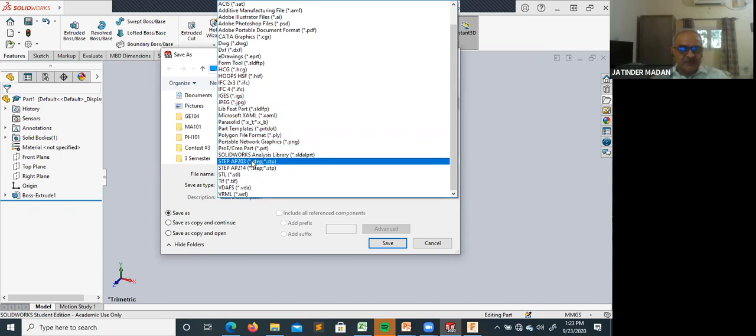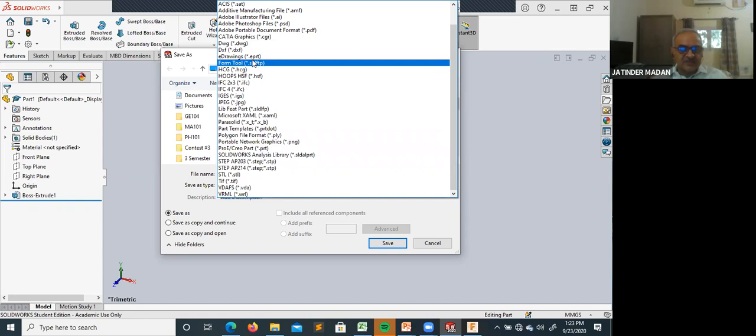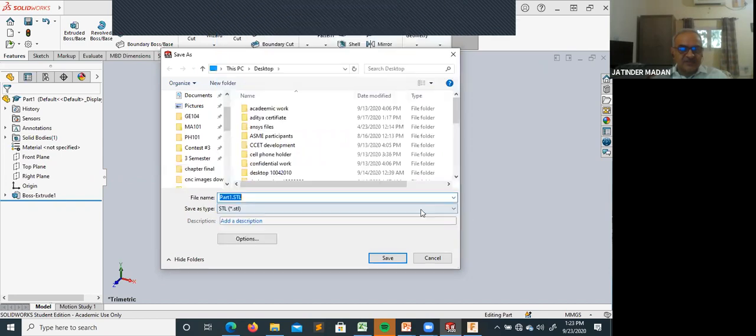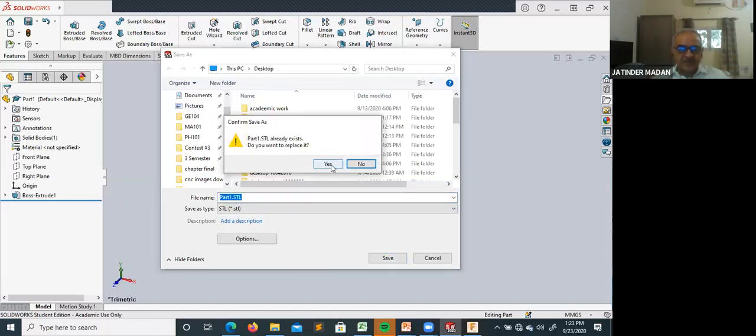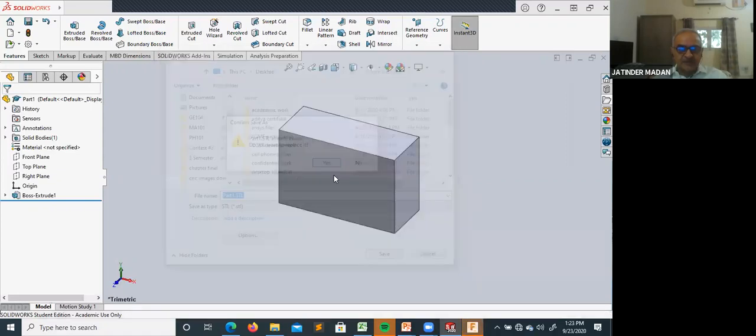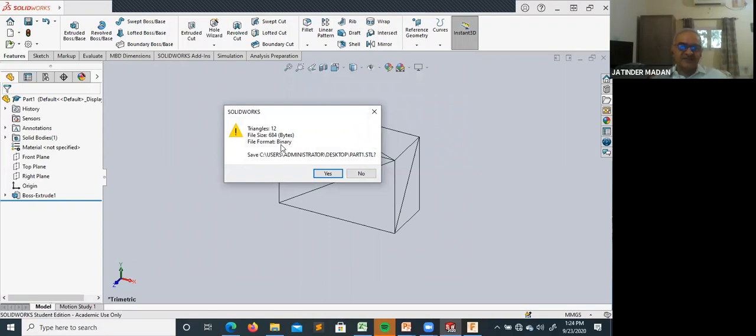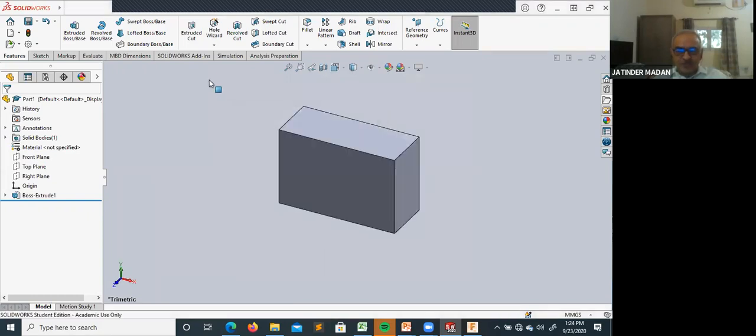And you have, let me see again, STL. It is not showing me the option, it generally shows the ASCII or binary format. Okay. So let me see, replace it. So this is saying binary. Binary means I won't be able to open it in Notepad. If you go to certain options, there must be some where you can say ASCII format. So it will give you the triangle by triangle. So 12 triangles, and for each triangle you have the start point, end point.